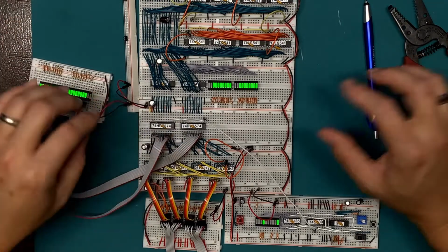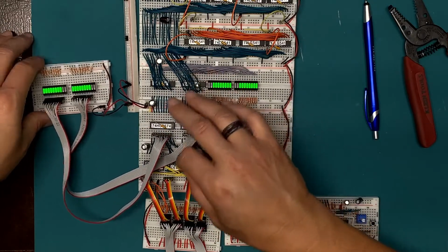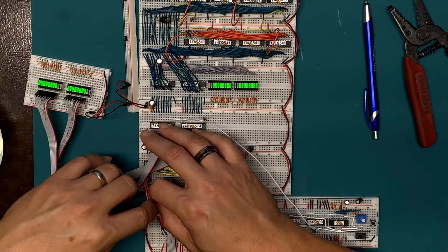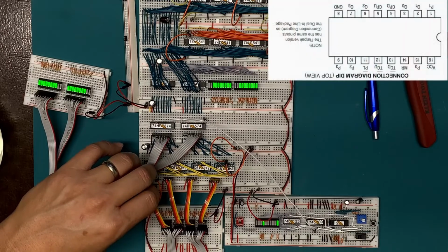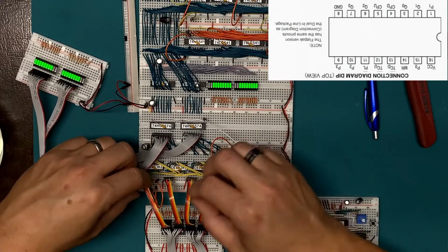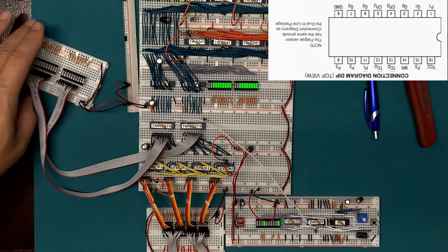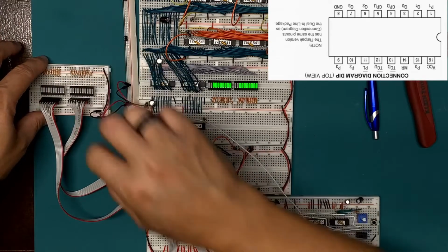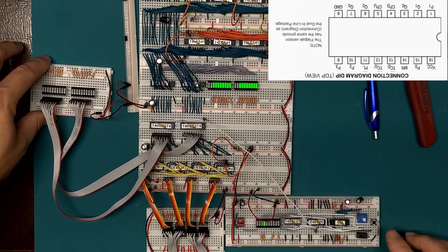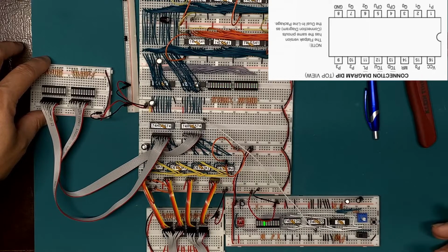Now the input into here, which is the output from these counters, I do want to reset. My master reset is on pin 14. So if this comes high, it should reset everything, and so it's reset the output off of these counters. And then if I clock that, I should see those return to zeros, which it has.